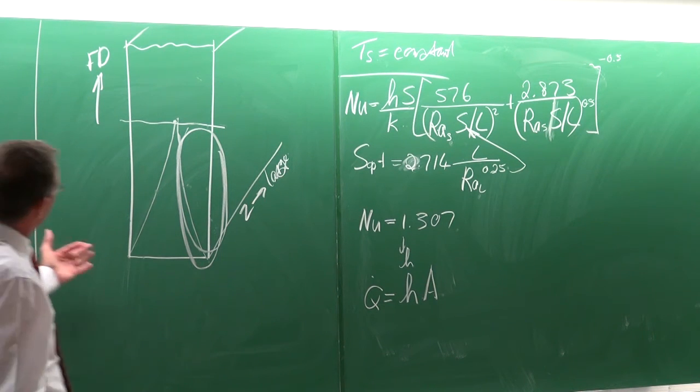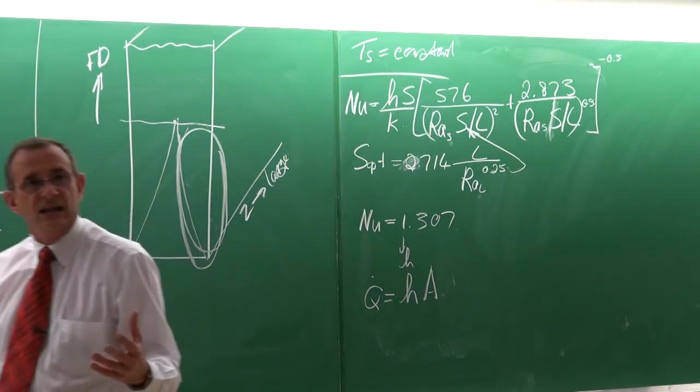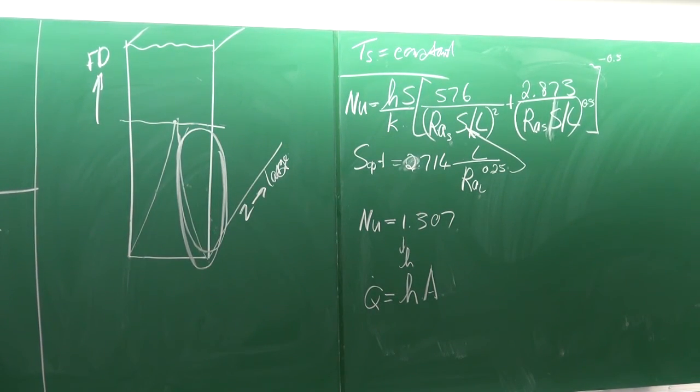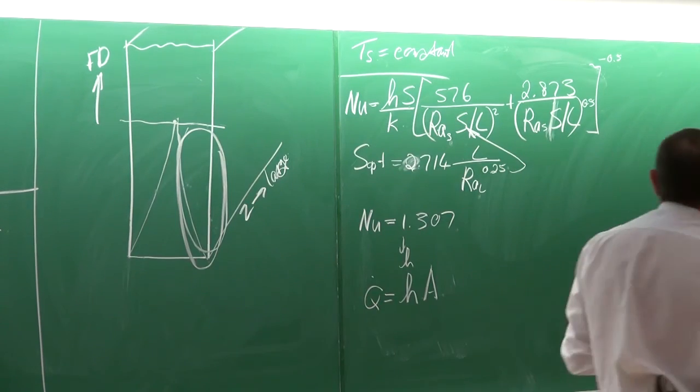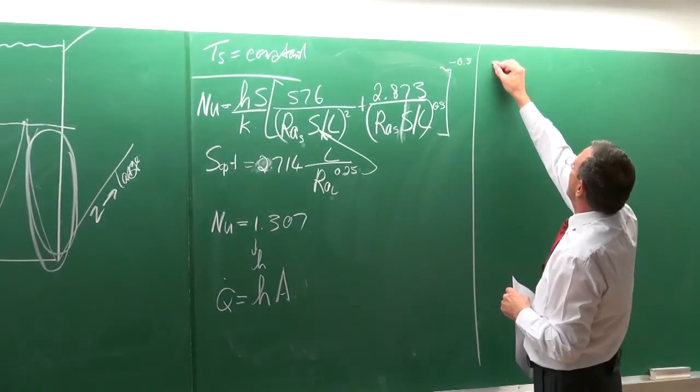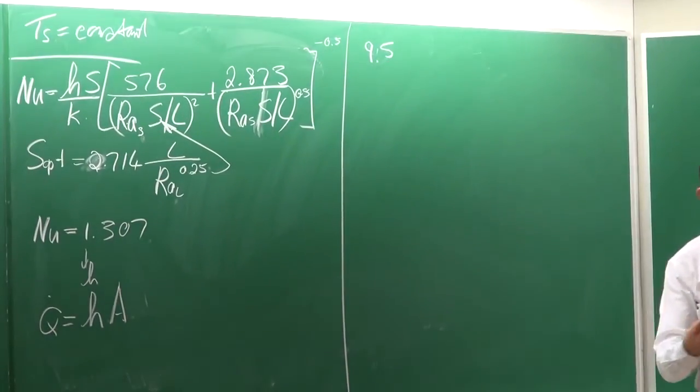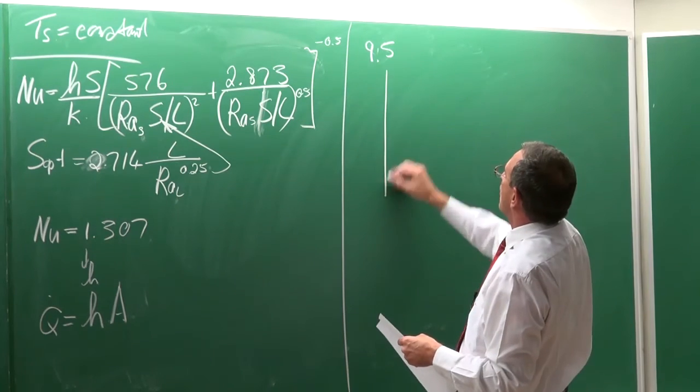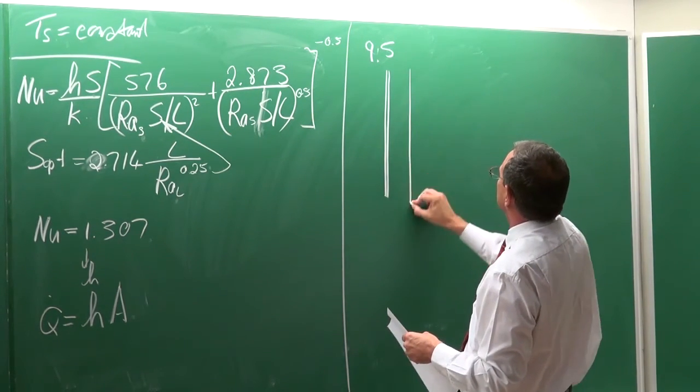Okay. So with that work, for example, you can go and get the heat transfer coefficient for fins, and the fact that I don't do an example about it doesn't mean it is not important. Again, it comes back to the principle of the Nusselt number as a function of Reynolds, Prandtl, Grashof. We cannot do every possible geometry on Earth. There's one more geometry that is important, however, that I would just like to say a few things about, and that is for enclosures. And that would be paragraph 9.5. And the classical example that is being used is, for example, an enclosure like this.